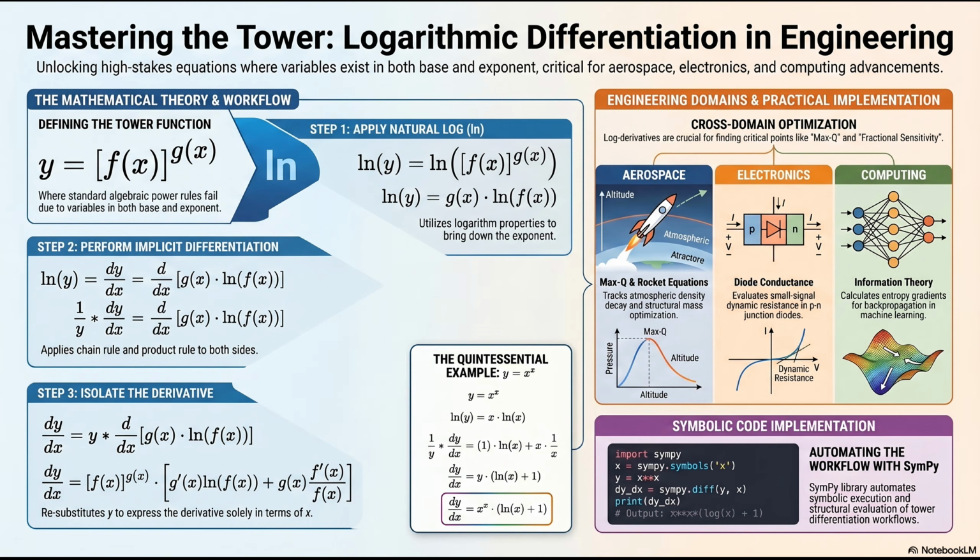Because the air density is dropping exponentially, but the velocity is increasing quadratically. You have these two massive opposing forces basically crashing into each other. And the intersection of those two changing forces creates this mountain peak of physical stress on the airframe. That is max Q, the point of maximum aerodynamic drag.